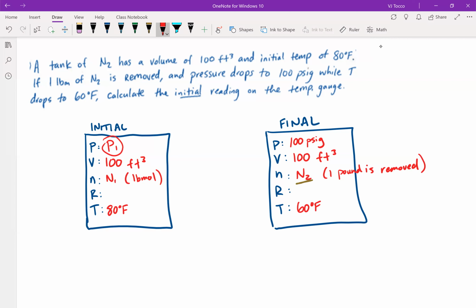Now, before I begin, remember, anytime I do an ideal gas law, so for the final situation, I can say that PV is equal to nRT. And since I'm trying to solve for n2, I could say that n2 is P2V2 over RT2. And I have all these numbers, but I'm not just going to simply plug in everything I've written so far. Remember that anytime I'm doing an ideal gas law calculation, I must have absolute pressure.